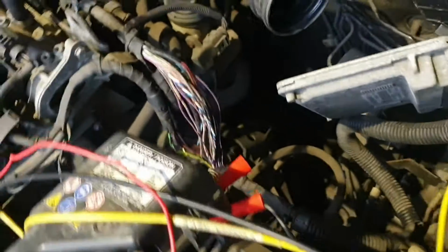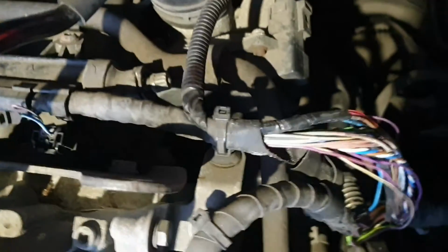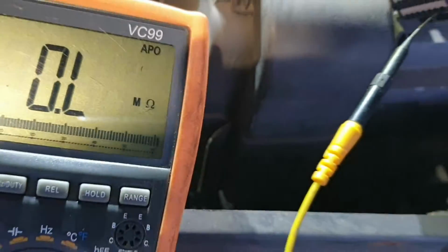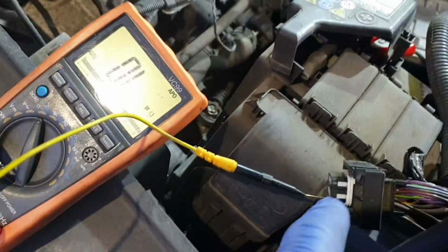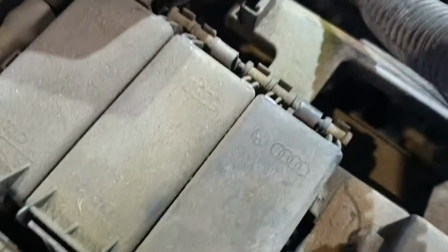Okay, now I'm going to find out where the wire is broken. This mess was not made by me. It had already been done by someone else. So I'm going to trace this control wire, find where it has been broken, and do the repair. As you can see, I'm going to do a continuity test. I have connected, just one second. Okay, I have connected. This is pin 79 at the small connector here, and it is this one.